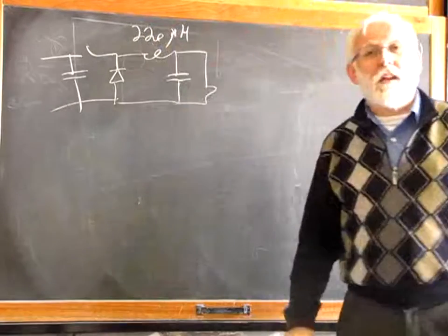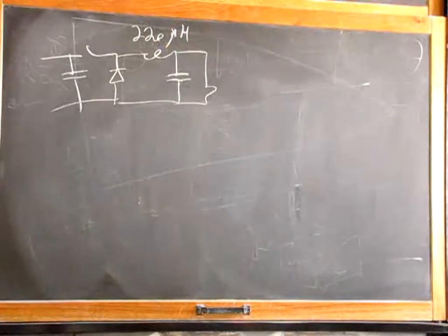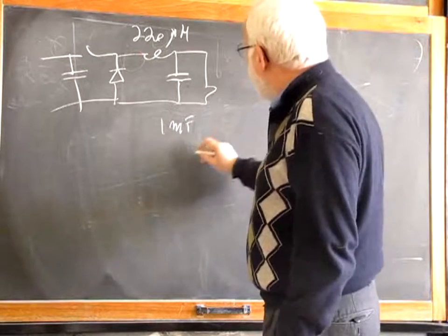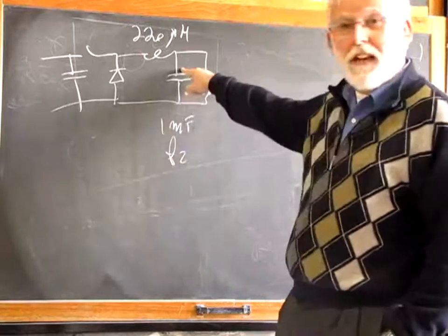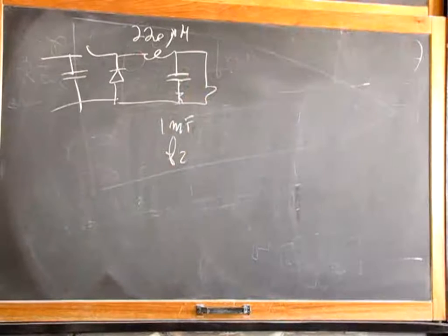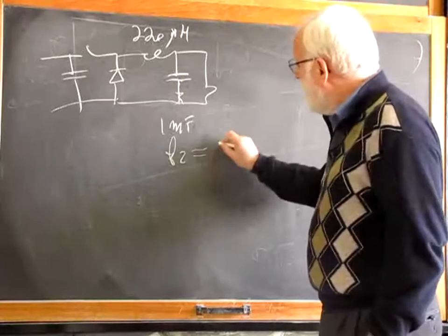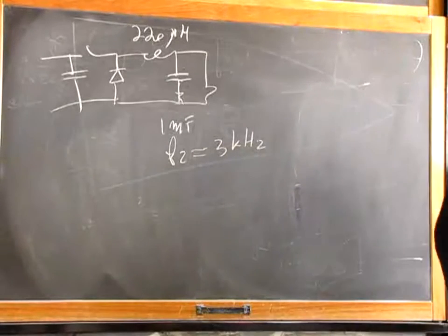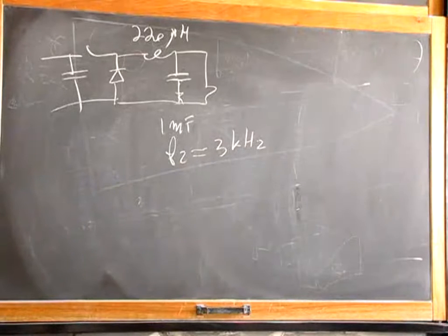How much is the output capacitor for the buck converter? 185. And it has a zero frequency, due to its ESR. Did you measure the zero frequency? Yes, maybe using the ripple, somebody of you did it. It was around 50 to 60 milliohms, and the zero frequency turns out to be around 3 kilohertz. It's not the best capacitor you can find out there, but it's not the worst either.